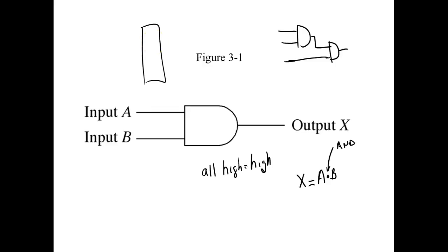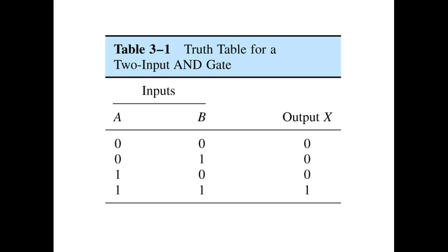So we're still confined to that. If it's a 14-pin deal, we've got 12 pins to work with. So the maximum we could possibly have would be 11 inputs and 1 output in a 14-pin deal. So you can't say as many as you want in an IC, but we can cascade these things and probably get as many as we want, right? And if you've got a lot of money and you're going to sell 1 million of these things, you could probably get a company to make you one that's got as many inputs as you want.